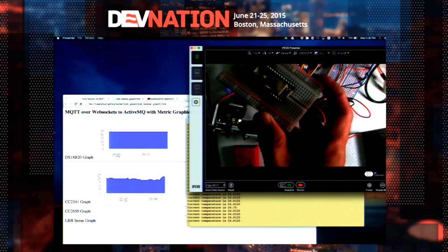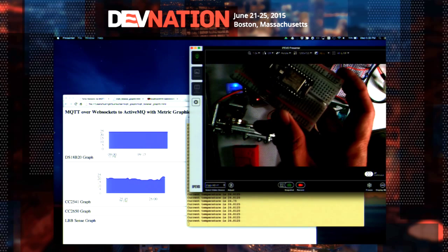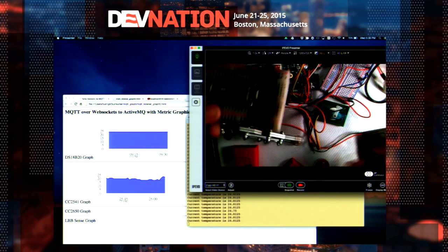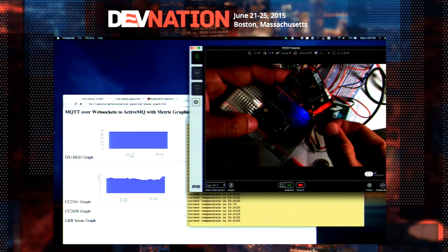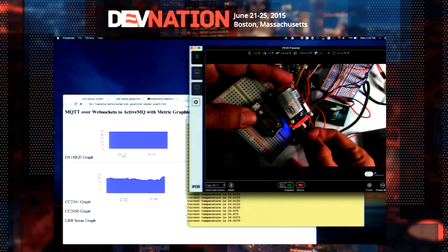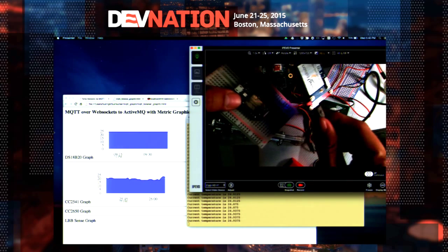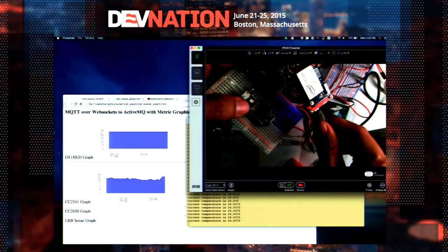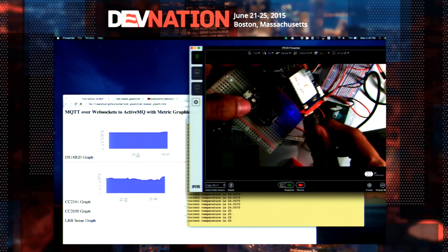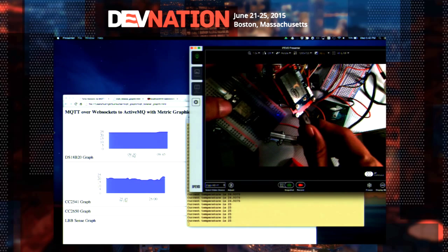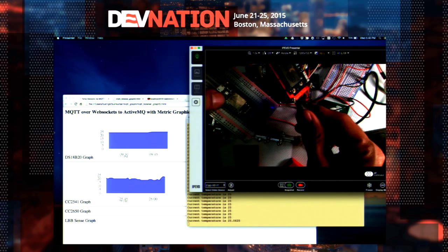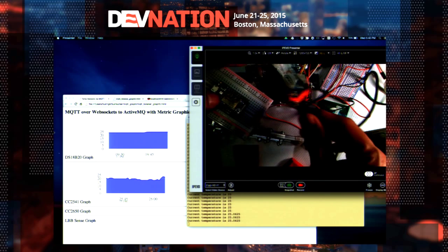You have 2 classes of smart things, by the way. You have the microcontroller and you have the Linux box. This is the way to think of it, right? Here's my Intel Edison Linux box. It's the same size as the microcontroller. The real distinction is your Linux box is not truly a real-time operating system. It allows for interrupts, right? If someone's downloading a big video from your Linux box, it's going to pause and download that big video. If it's supposed to be actuating a fan that's keeping the plant alive, that's problematic.